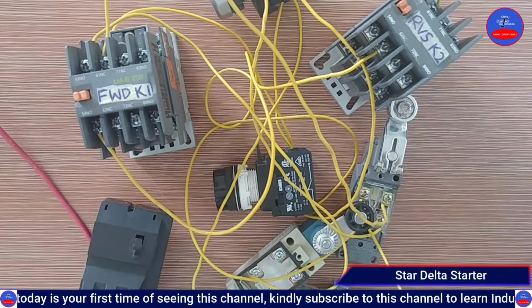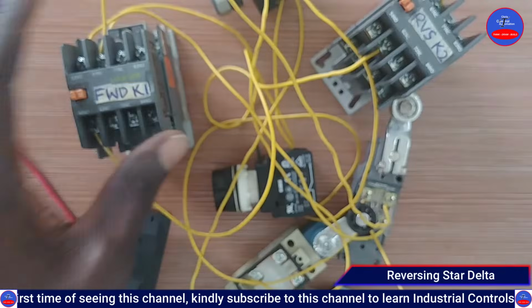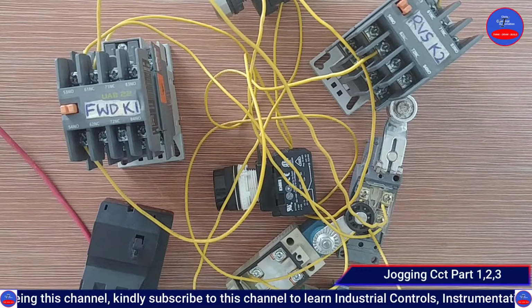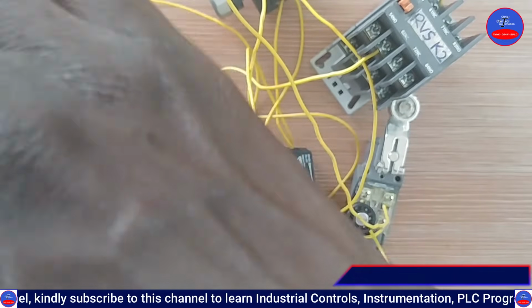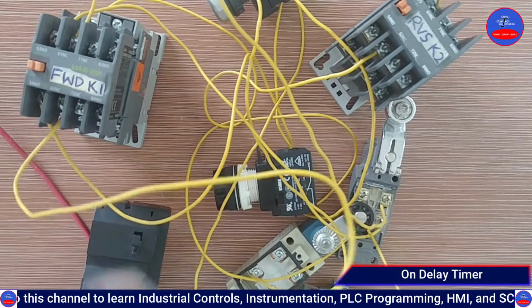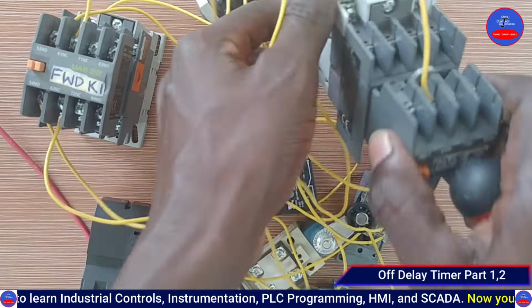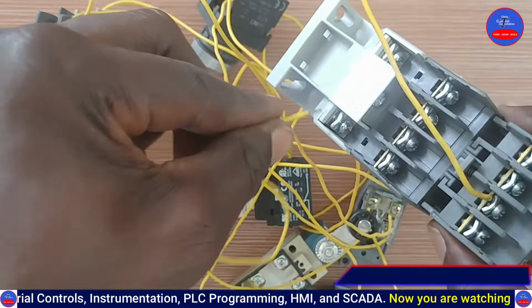Right, then from the other side, you're going to contactor 2, A1. So these are the auxiliary contactors we are doing. Sorry, this one is the interlocks. These are the interlocks. Contactor 2, A1. This is it. So we put it here.